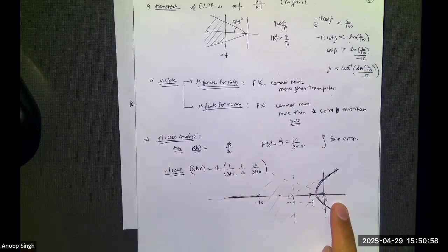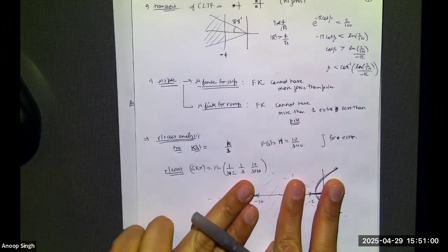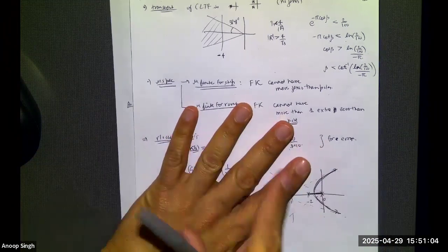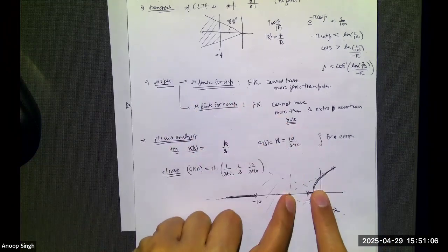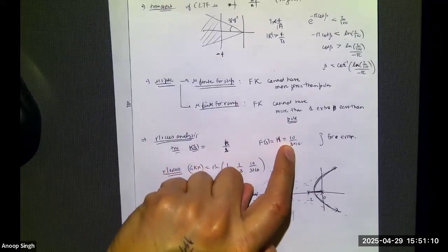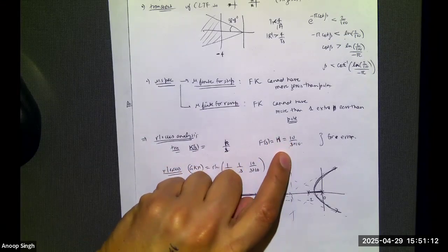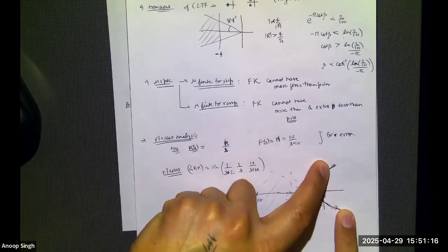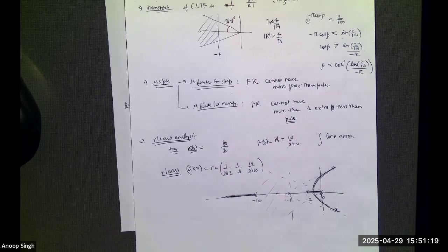So my closed loop system is 3 poles from here, 1 pole from the prefilter. Closed loop system is a 4th order system. 1 pole like this, other pole like this, 3rd pole like this, and the 4th pole is coming from the prefilter. So great, but my dominant poles, which are the most important ones, they're never in this region. So what should I do? What's my most favorite trick ever?